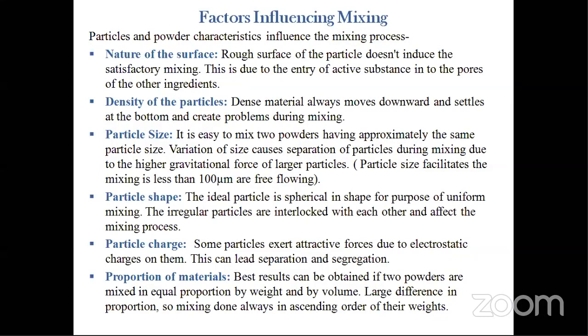So that's why we have to take a minimum amount of powder with a spherical shape. But sometimes it is difficult to obtain the spherical shape of particles, because the vendors supplying those particles do not specify whether the particles are spherical or irregular in shape. So first, it is checked on our side whether these particles are spherical or irregular. That's why we choose the mixing equipment depending on the particle shape.